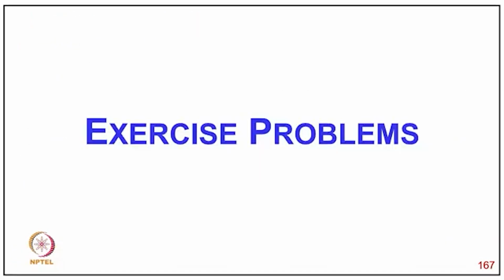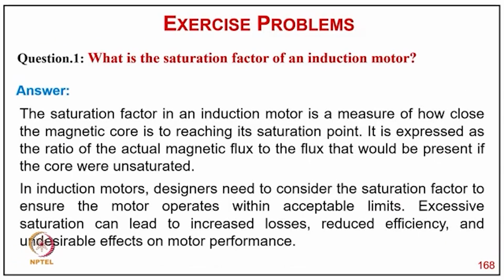Now coming to exercise and problems. So question 1 is, what is the saturation factor of a single phase induction motor? The answer is, the saturation factor in an induction motor is a measure of how close the magnetic core is reaching its saturation point. It is expressed as the ratio of actual magnetic flux to the flux that would be present if the core were saturated. Induction motor designers need to consider the saturation factor to ensure the motor operates within acceptable limits. Excessive saturation can lead to increased losses, core losses, reduced efficiency and undesirable effects on the motor performance.